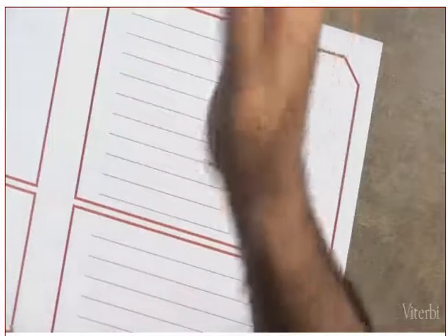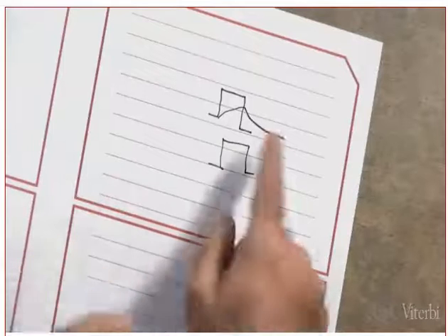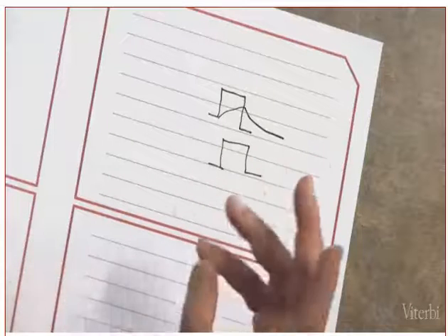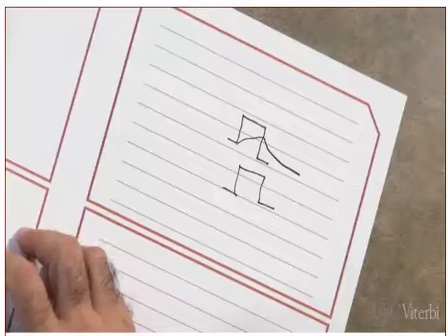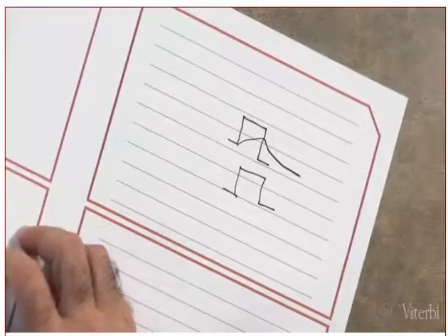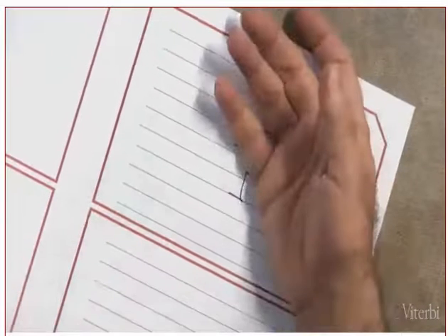You are interfering with yourself, not somebody else. Did you get my point or not? Because of this smearing. That happens when the bandwidth of the filter is smaller than the bandwidth of the signal. Did you understand what I just said?